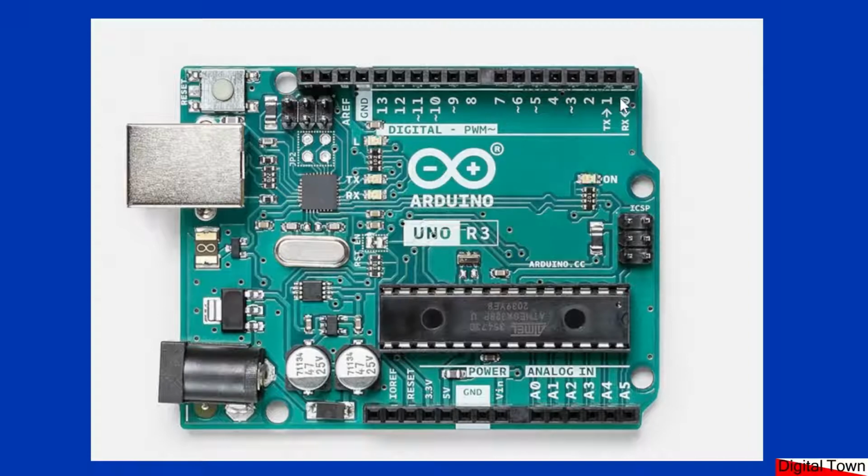Now those 14 pins, although they're all digital pins, what we tend to do is only use pins 2 to 13, because these two end pins, if you see, they've got a TX and an RX, and they are used for serial communication. And bizarrely, if you start to use those, you'll actually start to see the output of them appearing on your serial monitor if you've got it open.